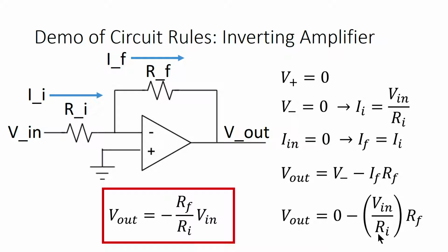Now just to describe this in exhaustive detail, the gain is equal to minus Rf over Ri, which is negative. So a positive voltage on V in will cause V out to try to produce a negative voltage. We'll have a whole video about op-amp power supplies later, but note that this op-amp would work really poorly if the negative power supply was at ground, because V out couldn't ever reach the value it was aiming for. It would just rail out at ground.